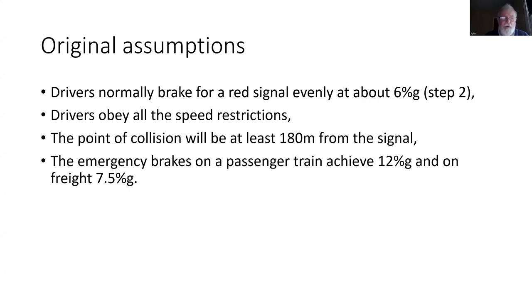It was also assumed that drivers will obey any speed restrictions. So whilst drivers might fail to recognise the need to brake for a red signal, because of their familiarity with the route, it is almost an automatic reaction to manage speed restrictions and brake for them. It is an assumption, and one has to be aware of that.